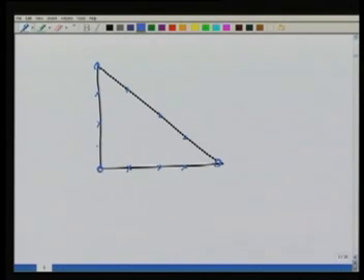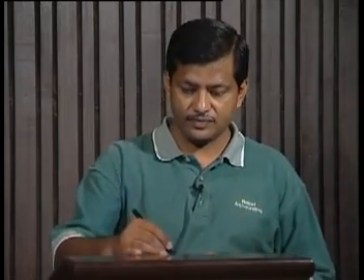here on these edges. So if you count all these points, I have 1, 2, 3, 4, 5, 6, 7, 8, 9, 10, 11, 12. So as far as the vertex and edge functions are concerned, or the side functions, there are only 12. So I need to have 3 more functions which are now internal bubbles. How do I find them? Very easy.